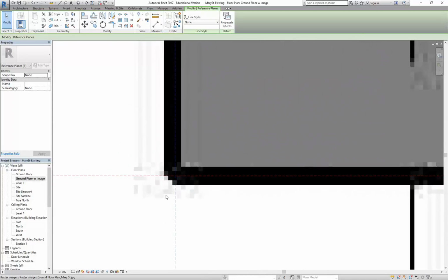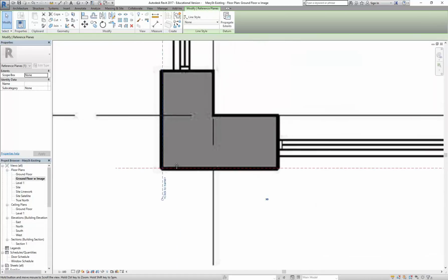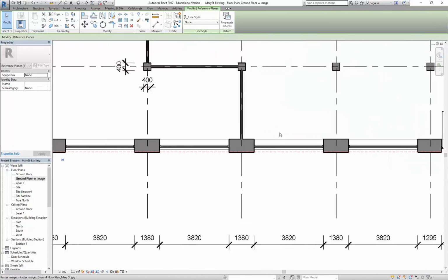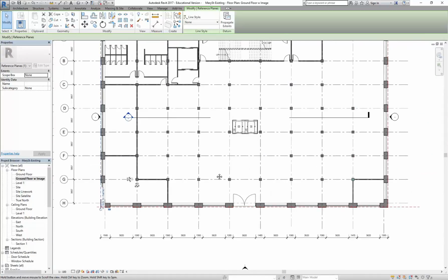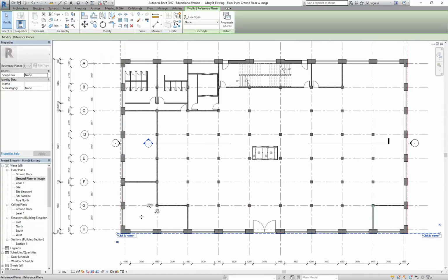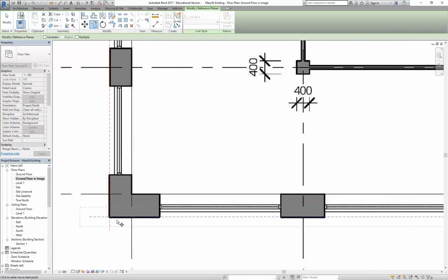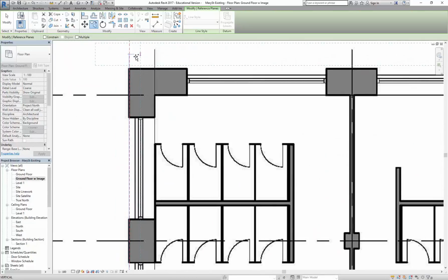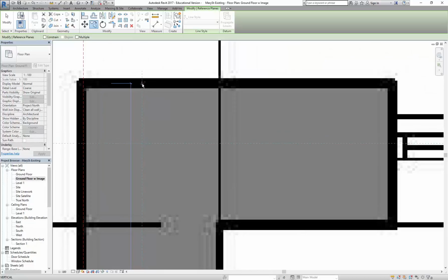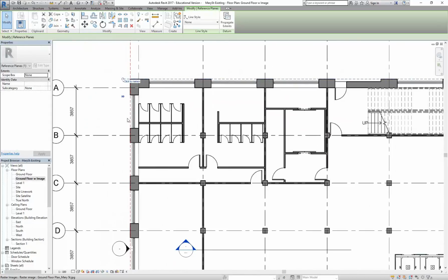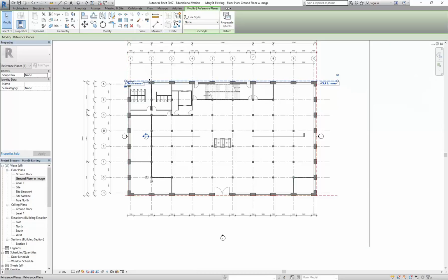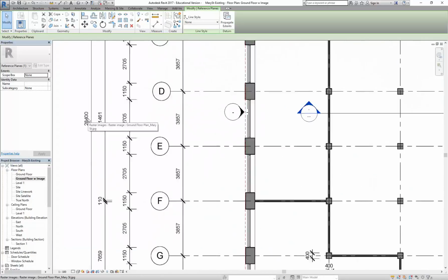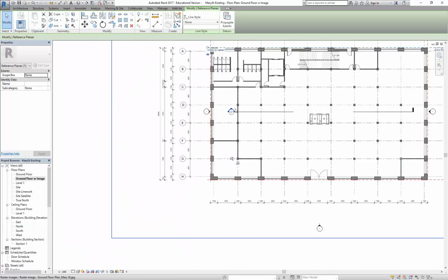And again, when you're zooming right in like this, you will start to think in that level of detail. So I've got a reference plane for the bottom, and then I'm going to just copy that. You could draw a new reference plane, but as with the lines in AutoCAD, I find it's easier sometimes just to copy things when they're going to be parallel. So I'm going to get that centered. And even though I've scaled the floor plan, that will not be the exact measurement. So just like the other one, I'm going to check what the measurement should be, 28400.